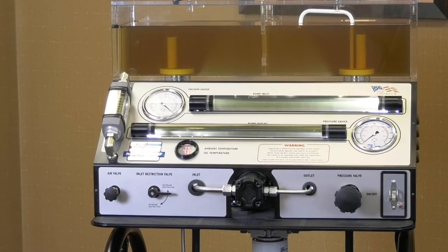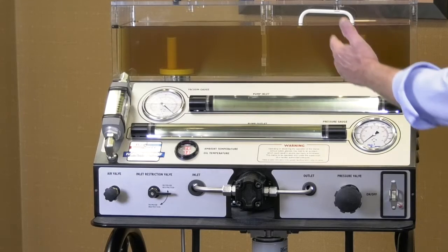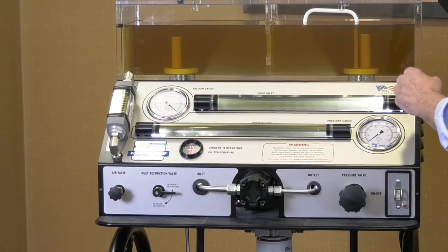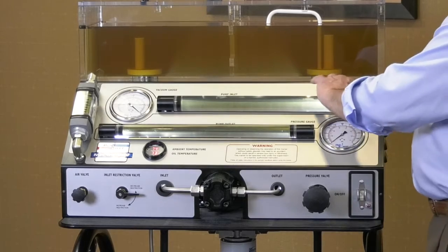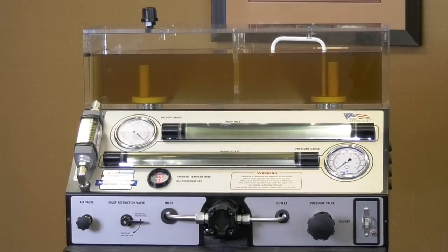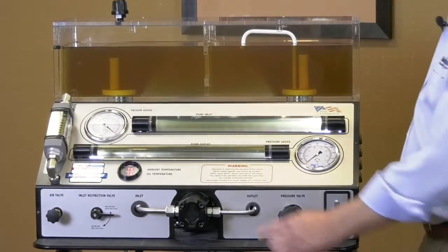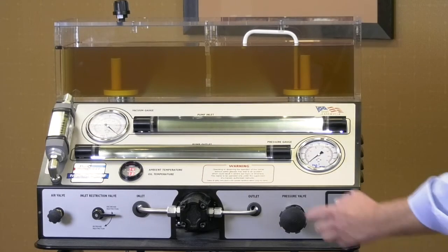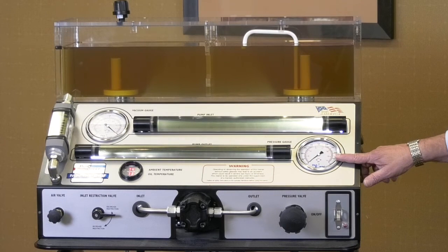So just a few things about the trainer itself. We've got a transparent hydraulic reservoir with a baffle which divides both the intake and the discharge. We have transparent intake and pressure lines. The larger diameter transmission line is the intake, the smaller is the discharge. We have a 1.8 GPM gear pump, a flow meter, ambient and oil temperature gauges, and a large vacuum gauge and a large pressure gauge.